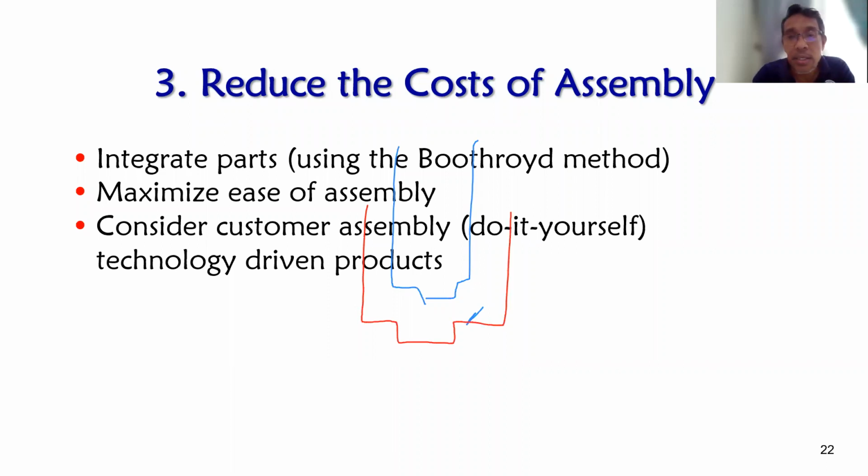So this one, you design straight, no chamfer. When we insert something inside this one, they need the self alignment to make the part go inside this hole. So you need to have a chamfer here, chamfer here.